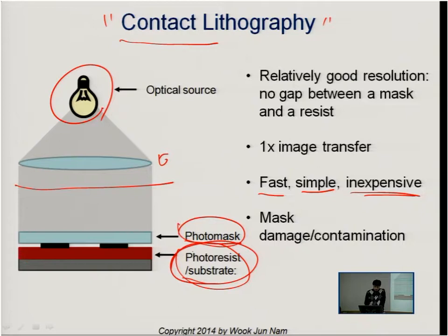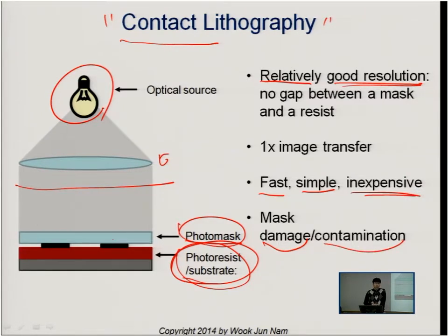And since this kind of photomask directly contacts the substrate, it offers relatively good resolution. But this contact of the mask to the substrate potentially causes some damage or contamination on the mask. So that's the drawback of this kind of exposure tool.